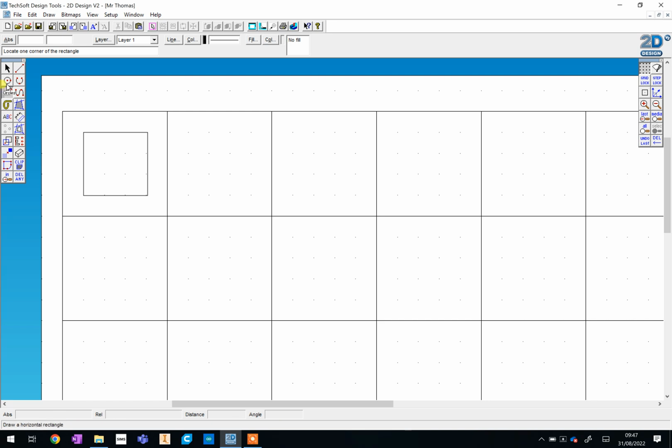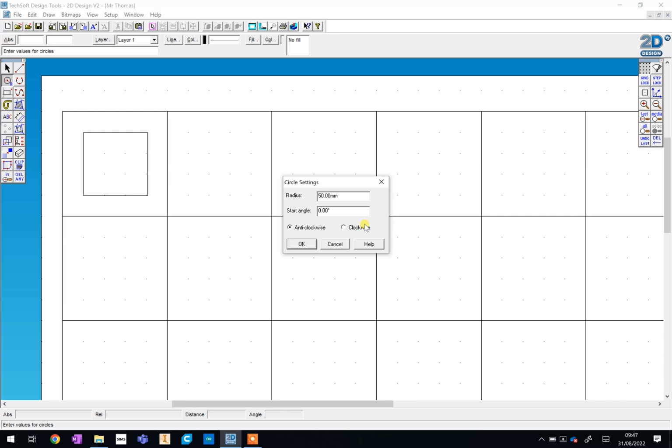So we're going to use the circle tool to do this. Now what I want you to do is to click on the circle tool and hold down the mouse button. It brings up all of these options for the circle tool. We're going to go to this next one here, the circle with the R next to it. That says draw a circle with a given center and radius. If you let go of your mouse, it will allow you to do that, and you get this little box appear down here.